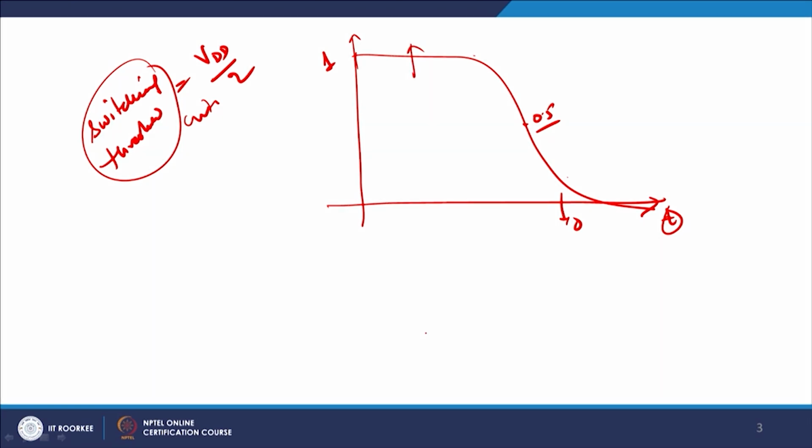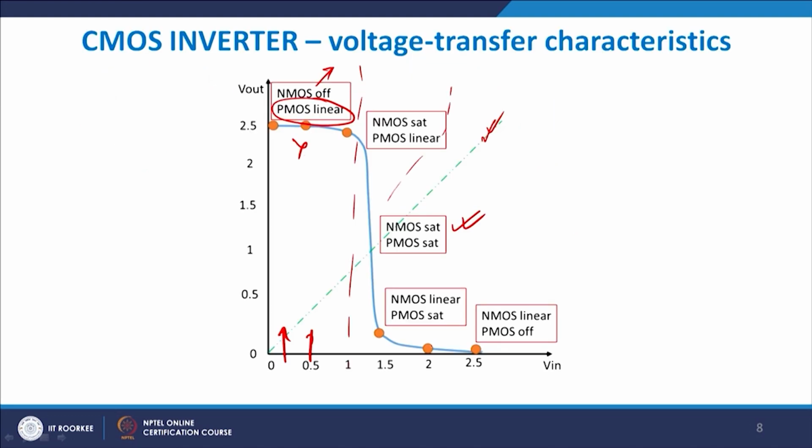So, we have understood the difference between the switching threshold and the positive switching threshold. We have understood the CMOS inverter working principle, the CMOS switching threshold, the meaning of switching threshold, and CMOS inverter noise analysis. We have also understood the basic principle that dVout by dVin should be 1, which means the amplification should be 1, for finding out the values of the